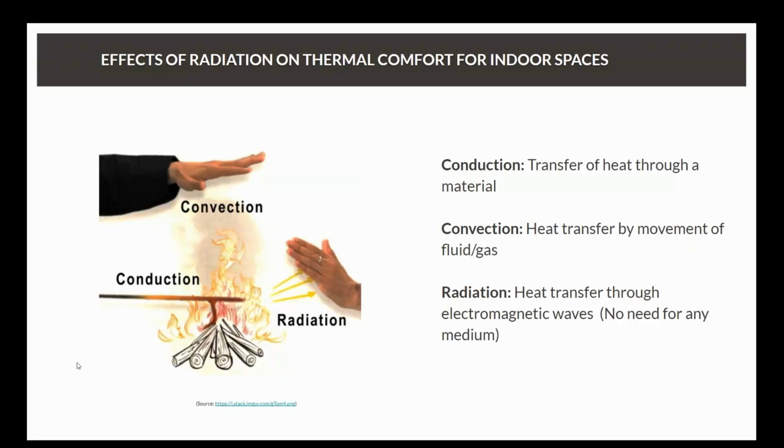And that could be through forced convection. So you might have air being pumped into the room, as we do in this scenario that we'll look at shortly. Or you might just have a natural convection scenario. Simply having a heat source in the room, as you can see with the person's hand getting a little bit warm, the heat is going to rise and the air in the room will move, albeit pretty slowly. It'll start to move around the room.